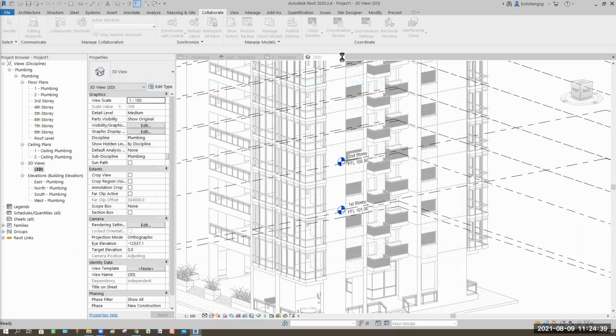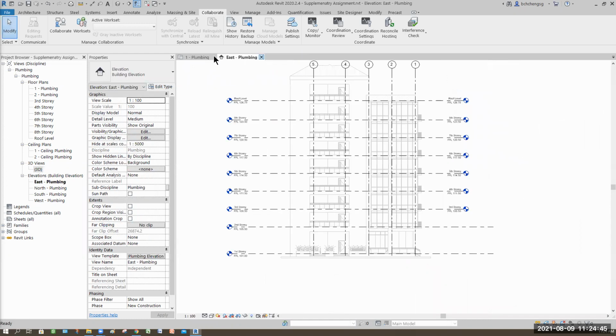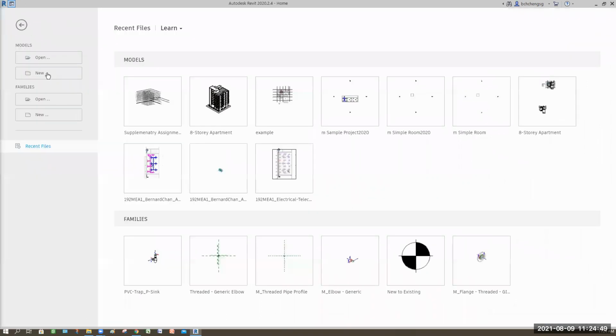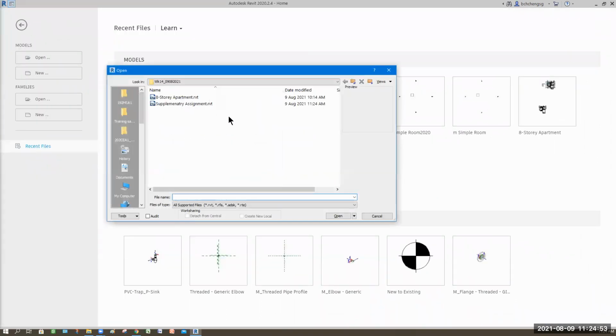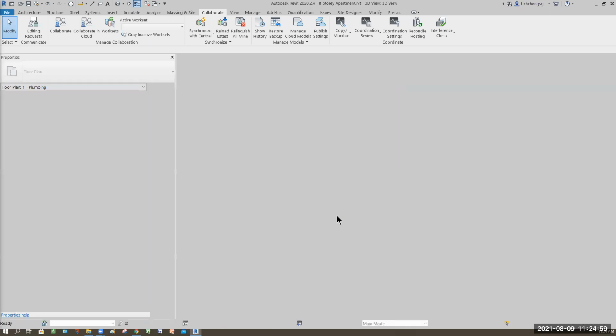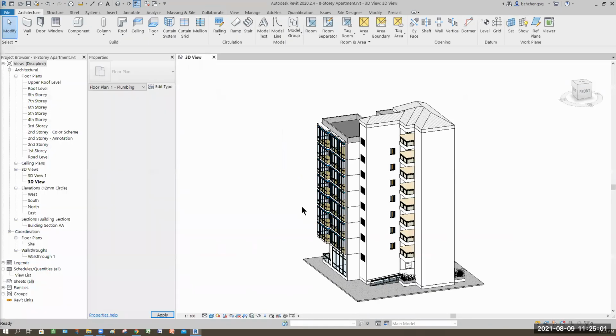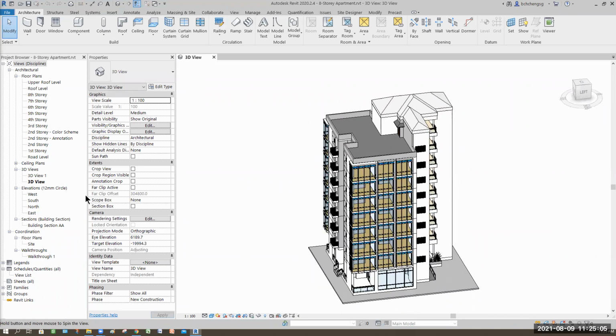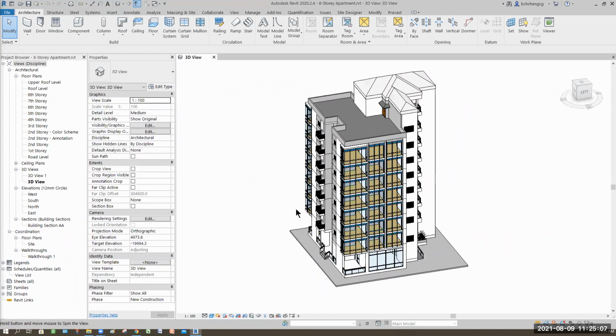Okay, so I save this. So I close it and open the architect file, because if you link the architect file here while it's still open, it will later be unloaded. So I will close first. Just open the architect file so that you can see the model. Where is the ceiling? That's why earlier on I mentioned, if you're not sure at the start, what you should do is enable section view.